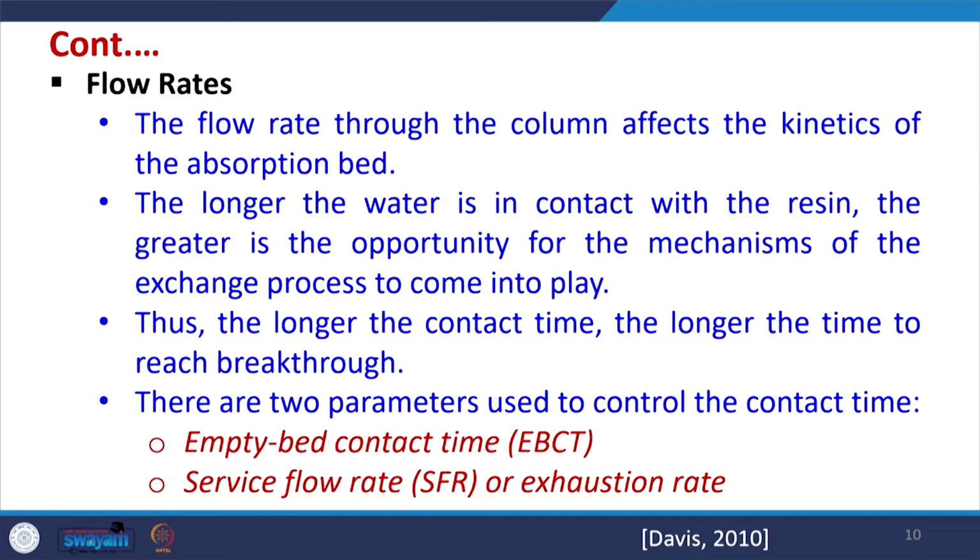Similarly, flow rates are also important, whether we are performing the operations at lower flow rates or higher flow rates. Flow rates always affect the breakthrough. If the flow rate is higher, the breakthrough will be achieved much earlier, and if the flow rate is smaller, we can achieve the breakthrough after much more time. It will affect the kinetics also. The flow rate through the column affects the kinetics of the adsorption bed.